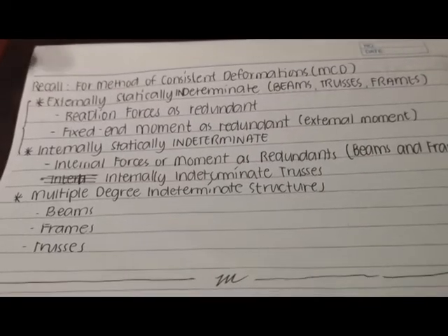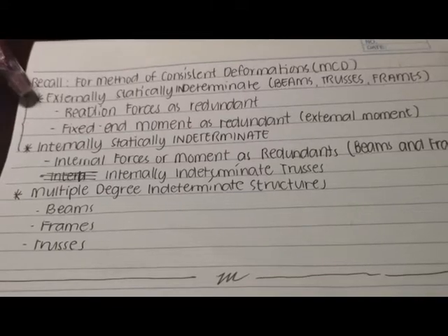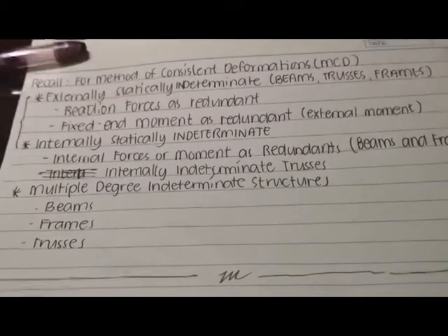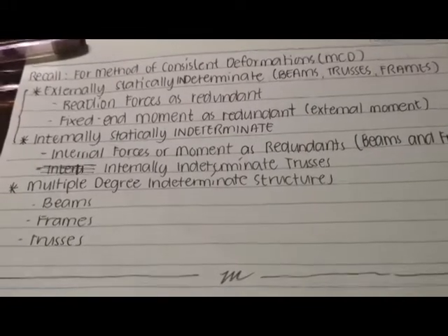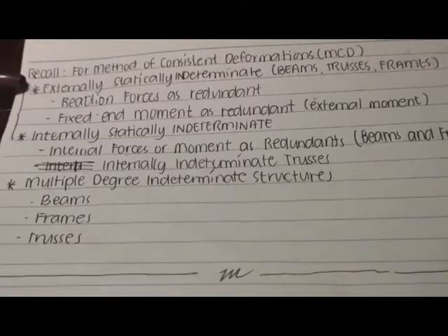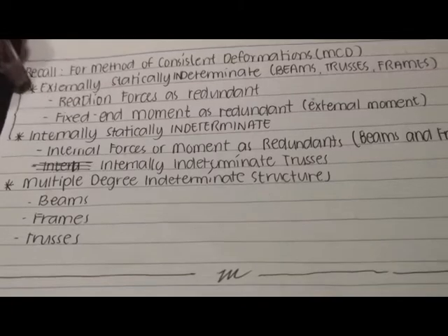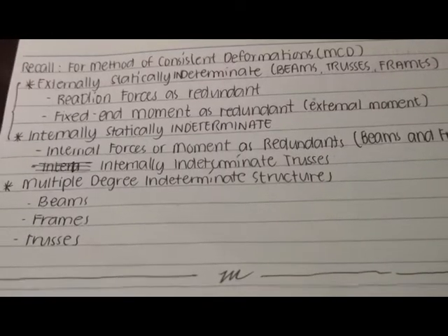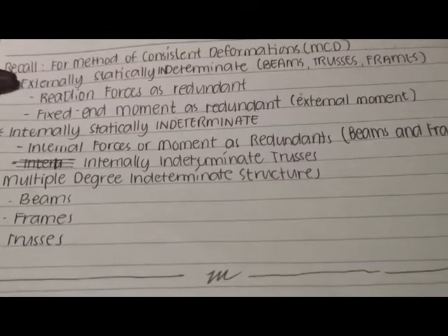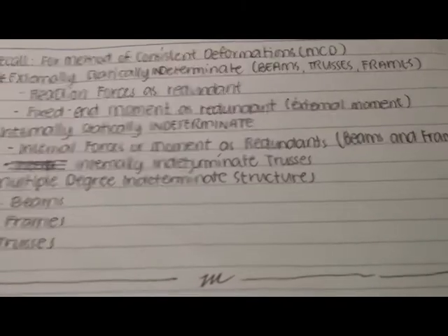So here is the breakdown of topics concerning the method of consistent deformation. So first, for a clearer illustration, we first solve structures with a single degree of static indeterminacy. And for single degree indeterminate structures, we divide it into externally and internally statically indeterminate.